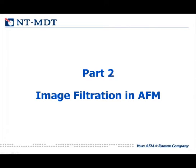So, image filtration. Why should we use image filtration? We are measuring our AFM images with a microscope. A microscope is an electronic device, and every time we talk about electronic measurements, we remember that our result contains both signal and noise. So the set of filtration methods is dedicated to removing noise and leaving our signal, our information about our objects.